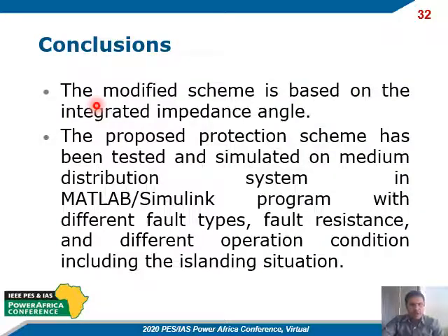Finally, some conclusions. Firstly, the proposed scheme is based on the integrated impedance angle, and it has been tested and validated on a distribution system using MATLAB simulation with different fault types, different fault resistances, and different operation conditions, including an island situation.